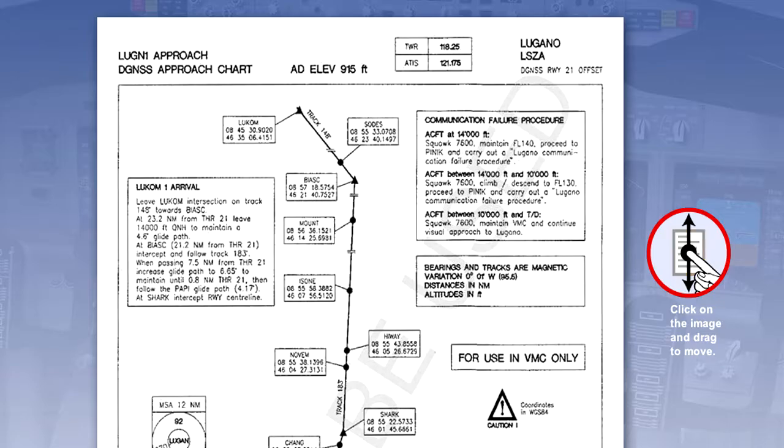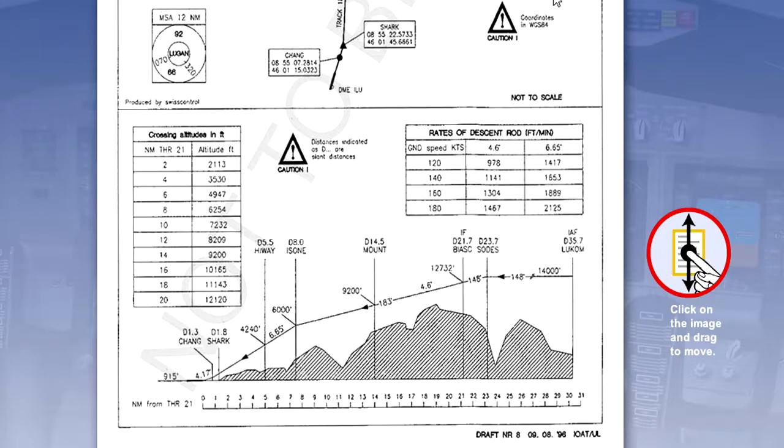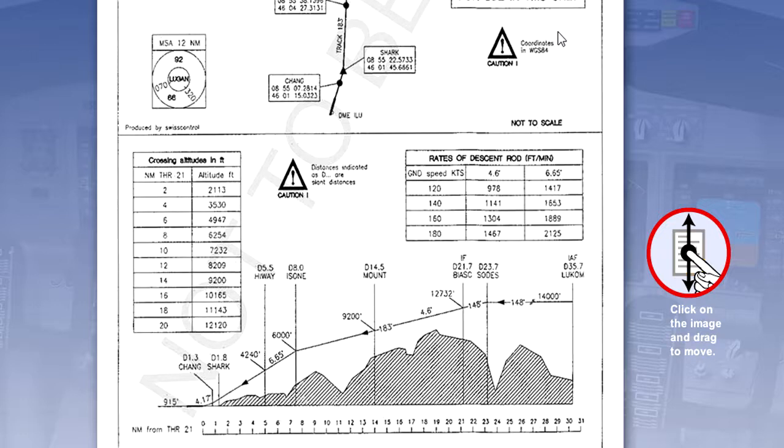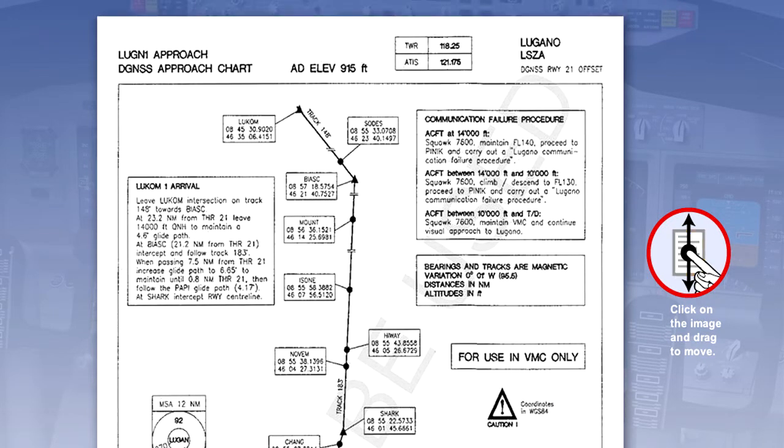The aim is to eventually replace VOR or DME with GNSS. These procedures will use precision RNAV, known as PRNAV, which may be augmented by altimetry cross-reference, Baro VNAV, to give the precision element to both arrival and departure procedures.